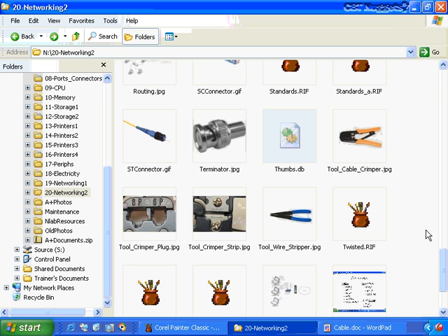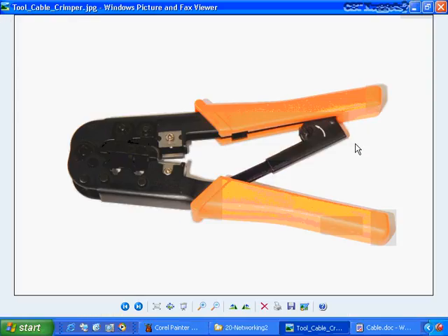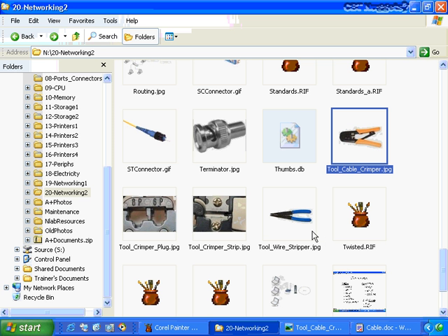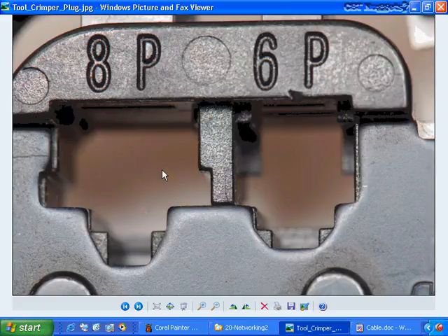Now, this is not an A+ exam objective, but let me just quickly address how you might create your own cables if you wanted to. You'd buy a spool of cable from a local computer store or electronics store, and then you can use a crimper much like this one. This is one of the ones that I have, and you separate all of your cable like you saw how the twisted pair were all separated earlier, and once I untwist all of those, I arrange them in a specific order, and what we will do then is to crimp them in the crimper like this.